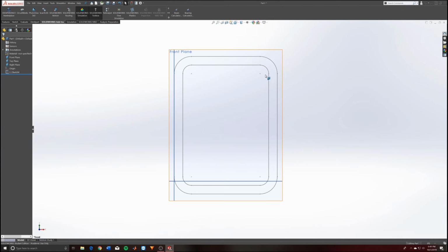So this is extremely useful, because a lot of the times there are standard dimensions for everything, and instead of having to look it up or go on GrabCAD to find the model, you can just make it right here. This is a really easy way, and then you can just go into the features and extrude it later. But that was a cool little thing I just wanted to show you guys, especially if you want to use standardized parts or structural members to design things. There's just a button to do it right here, and it makes your life way easier.